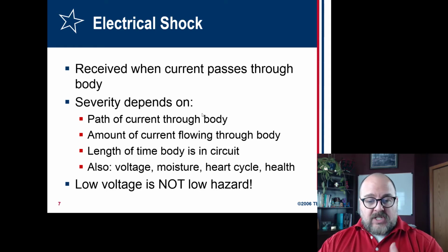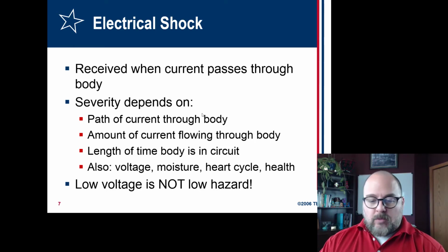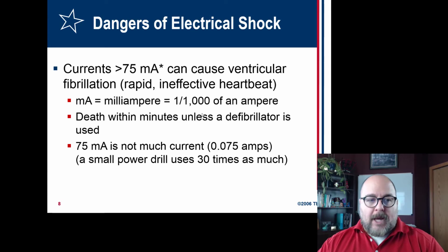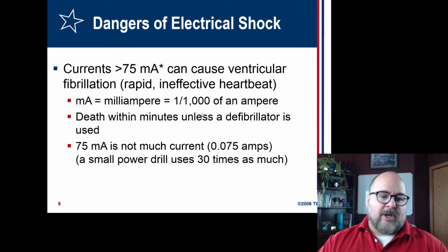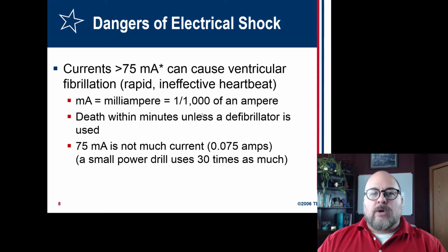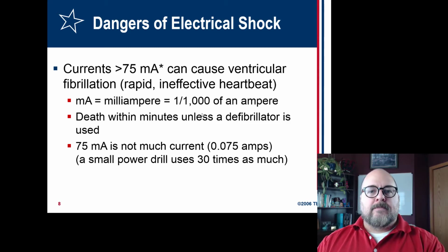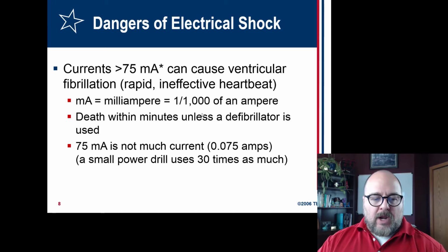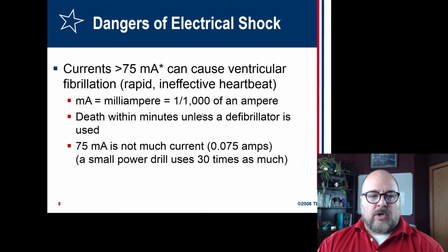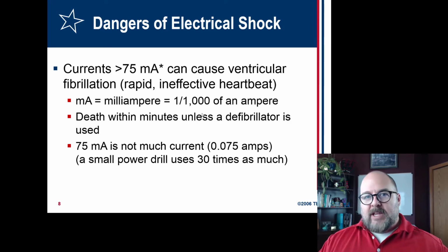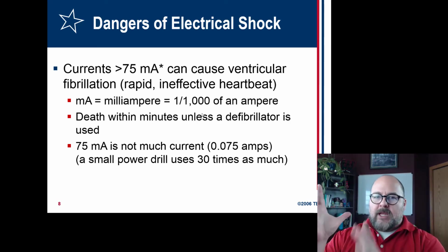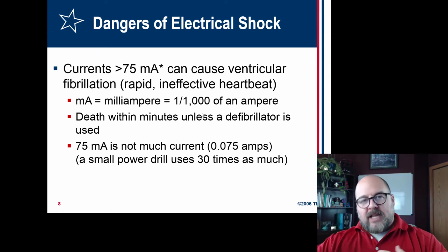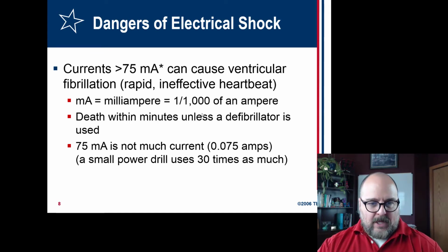And it says low voltage is not a low hazard. That's true. It just depends on where it enters the body and where it leaves the body. Currents as low as 75 milliamps, and down at the bottom I showed you what that is, that's 0.075 amps. That's a very low number. It can cause ventricular fibrillation if it goes through the chest cavity. I mean, if you have an electric current that goes from your pinky to your thumb, it's not going to do anything to your chest. It has to flow through your chest to cause that.